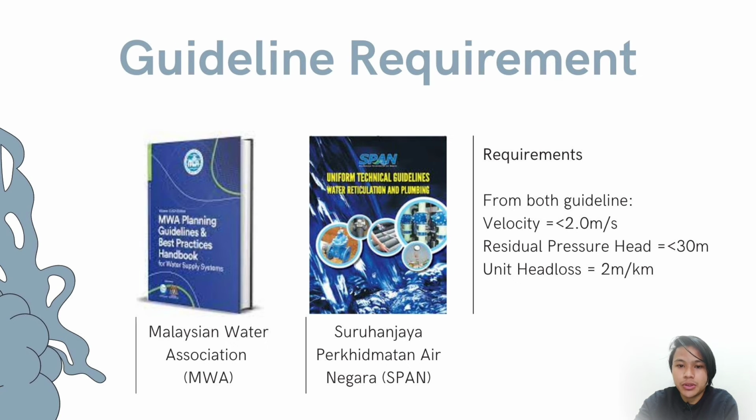Last but not least, I wanted to mention that the minimum amount of pressure head needed at the first node, based on what we have calculated, must be at least 7.5 meter to make sure water demand can be supplied to the whole node in the entire region.